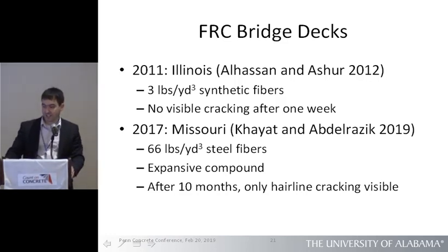In 2017, they added 66 pounds of steel fibers and an expansive compound, not necessarily a shrinkage-reducing admixture, a calcium oxide-based expansive compound. After 10 months, they only observed hairline cracking around embedded sensor trees. This was a smart bridge. It only cracked where they were sticking stuff in the concrete, nowhere else in the deck. And so fiber-reinforced bridge decks and pavements have been shown to have, at least within 5 years of service, good performance compared to not reinforcing it.